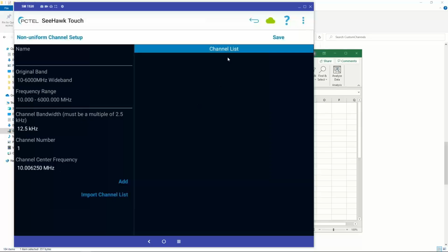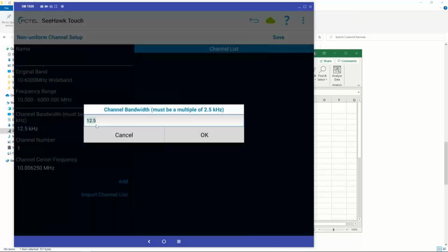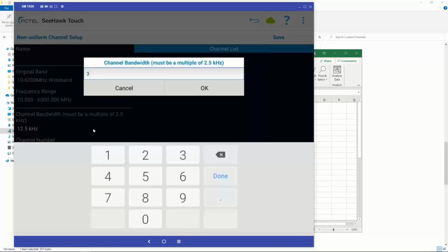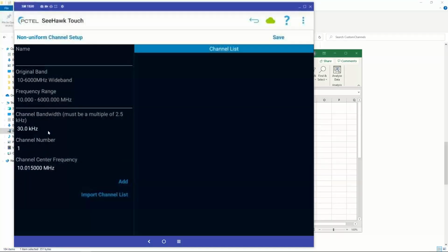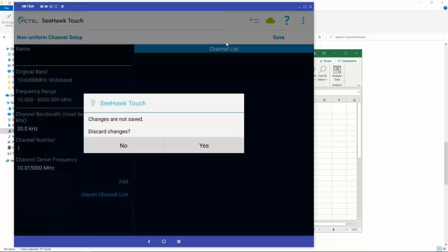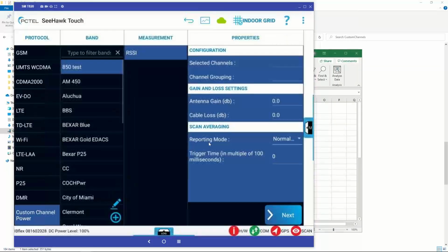I can create it. Well, if you're doing a constant carrier test somewhere, you're generating your own signal. Exactly. This is where you would set that. And if you're using a test transmitter, most test transmitters have either a 25 or 30 kilohertz wide generated signal, so you can adjust for that here as well. Yep. So if we want to put in an 800 carrier and go walk a building, just to test how it would behave, that's where this would come in handy.